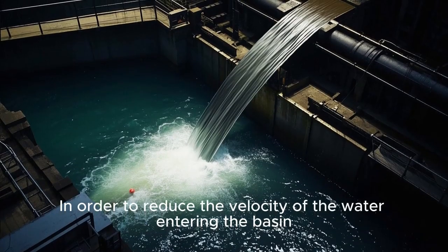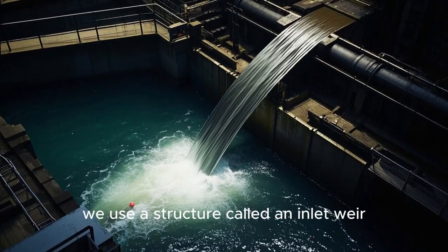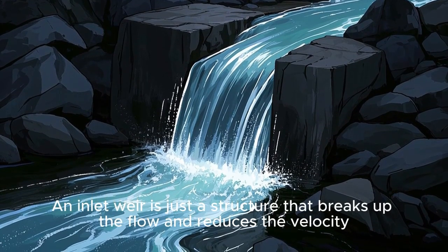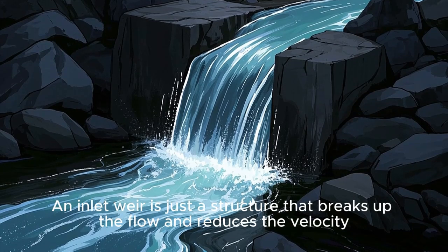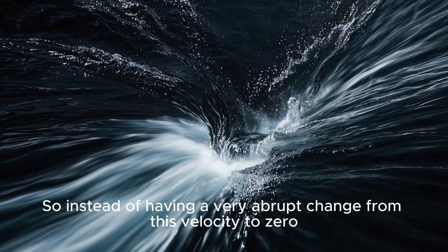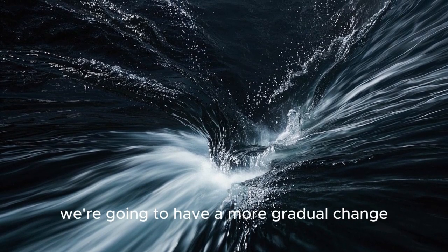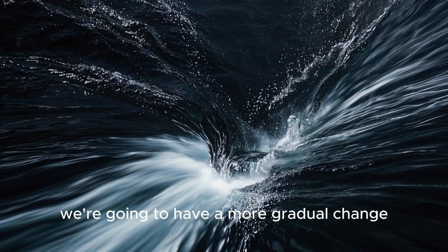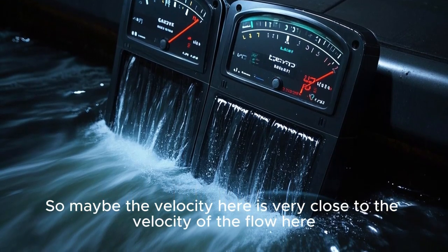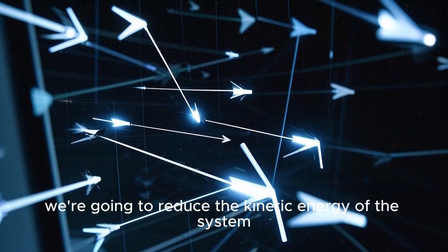In order to reduce the velocity of the water entering the basin, we use a structure called an inlet weir. An inlet weir is just a structure that breaks up the flow and reduces the velocity, so it makes the approach to the basin much more gradual. So instead of having a very abrupt change from this velocity to zero, we're going to have a more gradual change. So maybe the velocity here is very close to the velocity of the flow here, and by doing so, we're going to reduce the kinetic energy of the system.